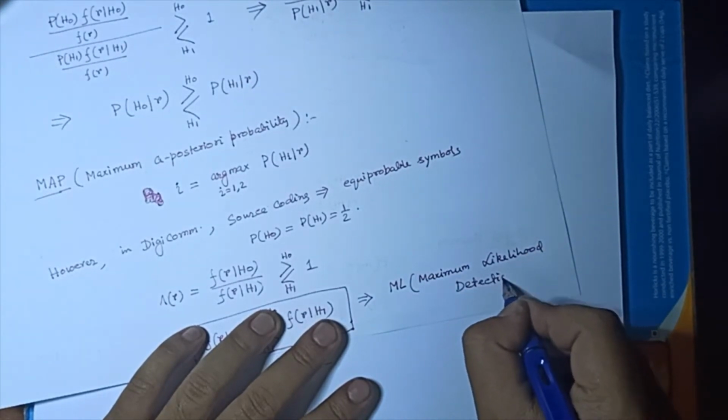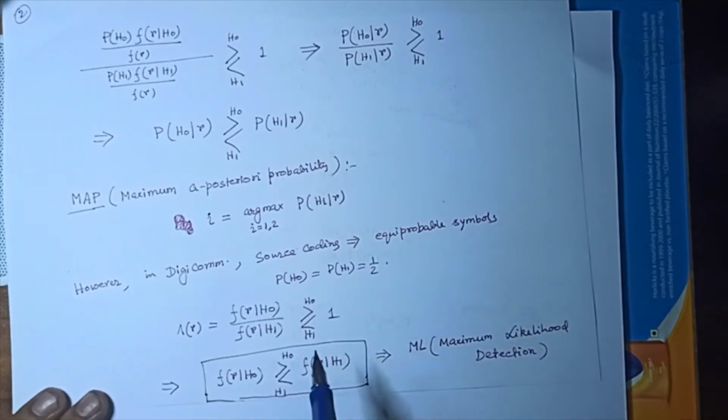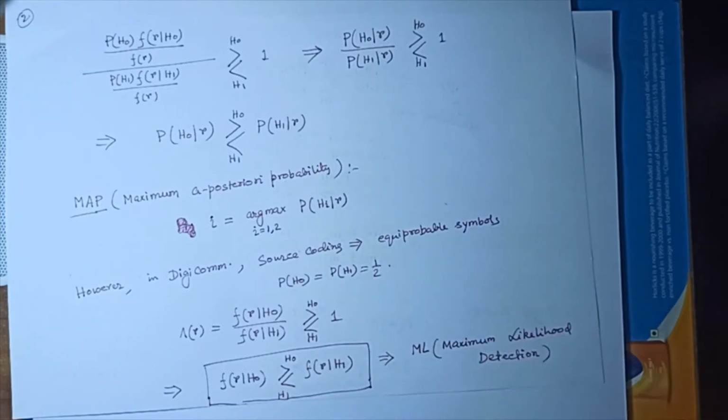So these are the two paradigms you can say in detection theory, where one is based on the Bayesian approach, where you compute the maximum a posteriori and you work on that. Another is like in the communication setup or in the radar setup, where you don't know anything about the prior, you have no idea, like biomedical setup, so you do not have any idea about the prior. Then what you can do, it is a natural process, you can assume that that is maximum entropy, and maximum entropy for a finite discrete random variable is equiprobable. So then maximum likelihood is the setup.